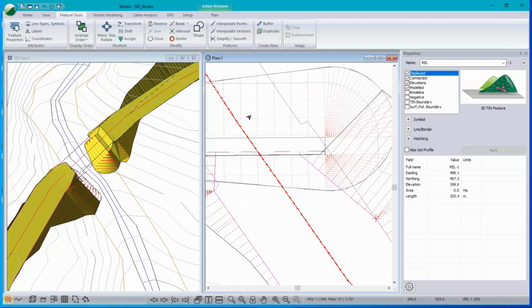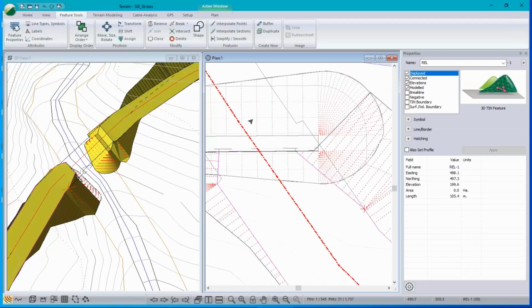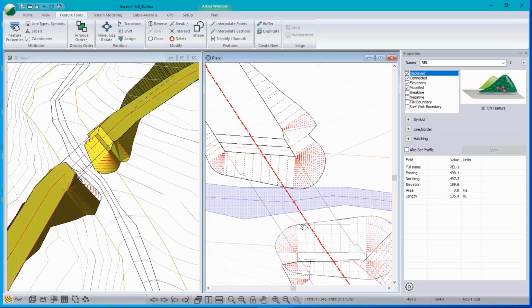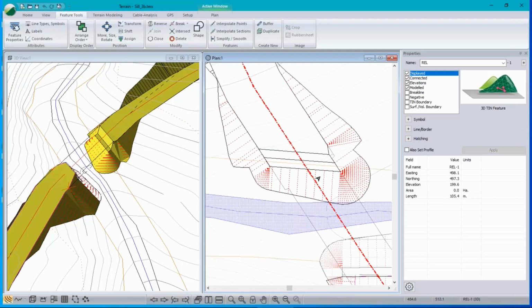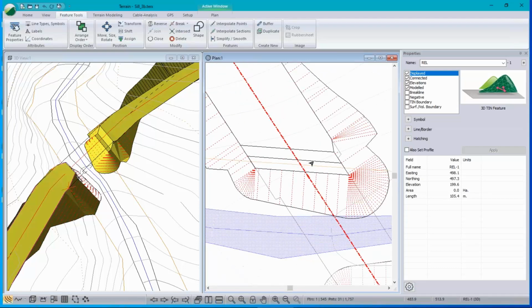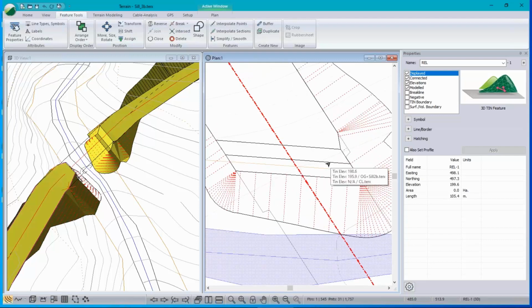On the other side, I actually drew the lines down and over like that, and I was very careful about setting the elevations correctly, putting in break lines, and making this three-dimensional object that looks like fill with a step in it, ready to put my beams on there. And again, I graded them out using the terrain modeling grading tool.